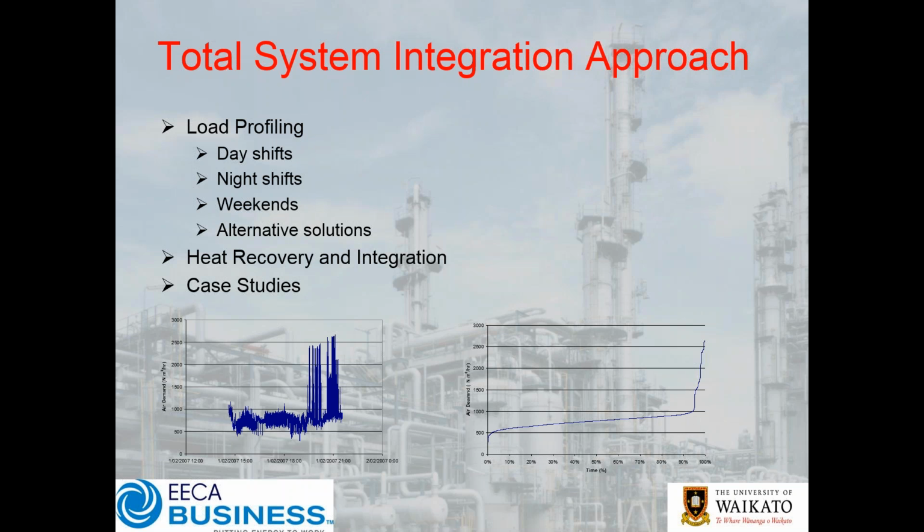So like you mentioned, the loading on the ID fan, be it reduced energy loading, it could be that you can slow the thing down, so then you've got less risk in terms of maintenance. Everything's running at a slower speed, so your bearing loads go down, your vibration levels go down, all those sorts of things. Or the other thing you could look at is that we can leave the fan as it is, but get more capacity, depending on the nature of your system. And it's those sorts of added benefits that you'll probably need to get the project close to happening.